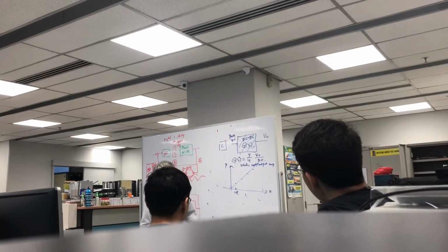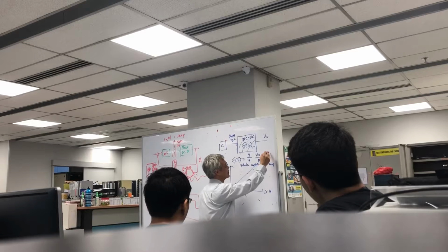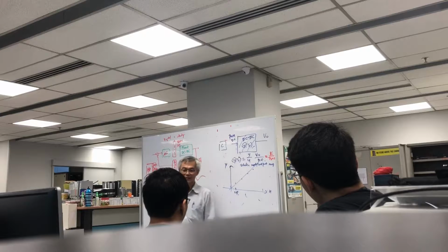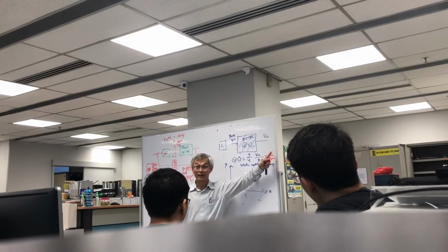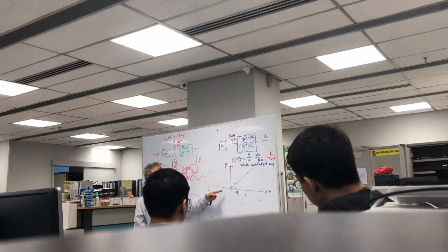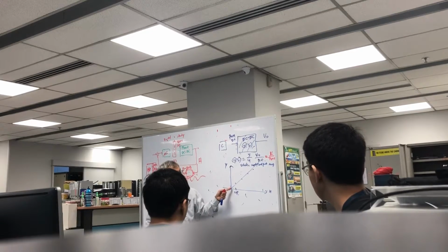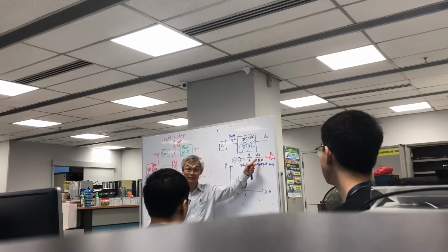You see, this is a transfer function, right? Just make it more concrete. Suppose it is a first order transfer function. What does this line tell you? Or what does the gradient of this line tell you? The gain, the static gain, K. Alright? So if you have a line like this, then you can say that the plant is so-called linear, or in other words, the gain is the same throughout.